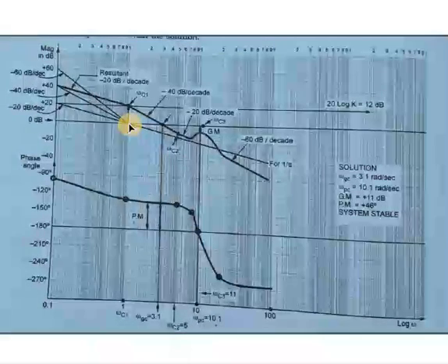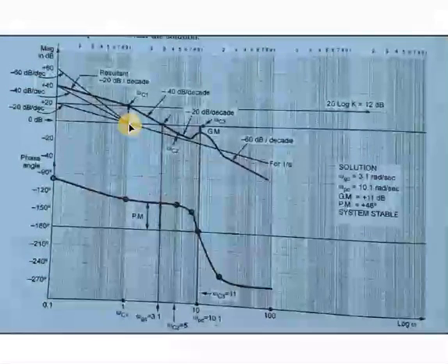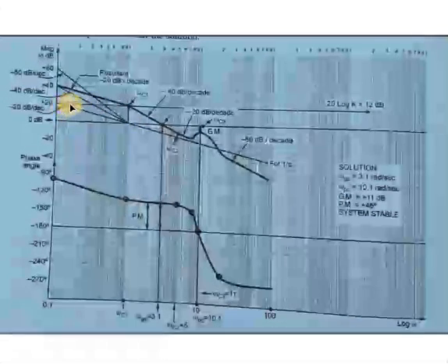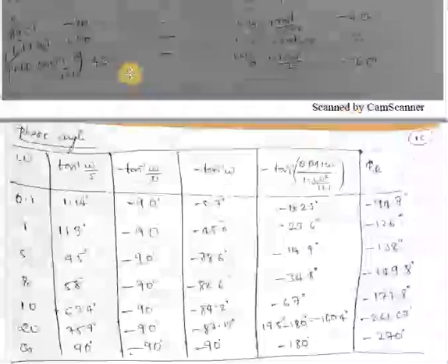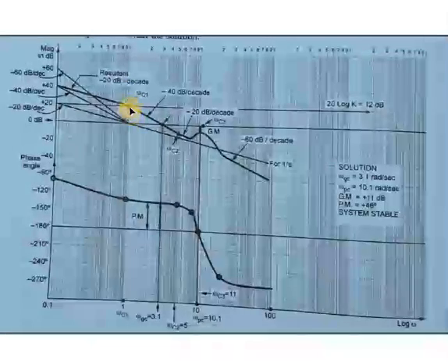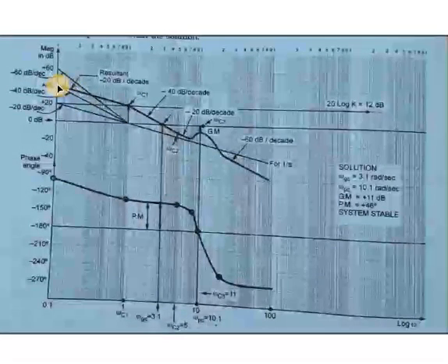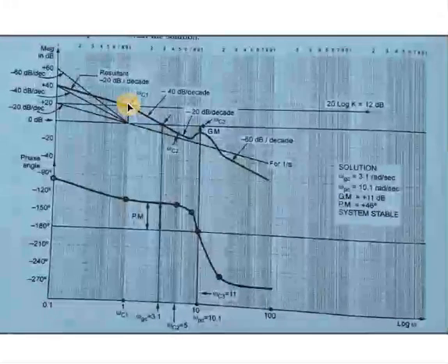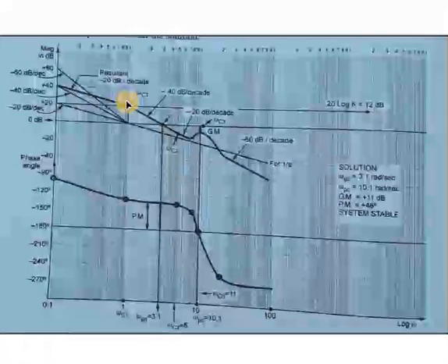Then you need to shift this point on the magnitude line. So the magnitude value is 12 dB. So at 12 dB, you draw one more line. Sorry, is the magnitude here 20 dB, not 12. So at the 20 dB line, you shift this point. That means starting from this end up to the point which is on this magnitude line will be the 20 slope only, and it will continue up to the next break frequency with the same slope.